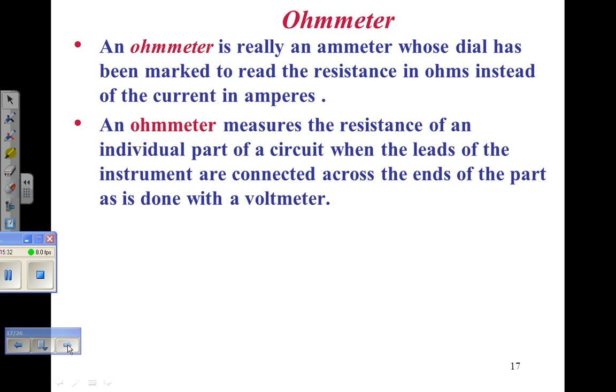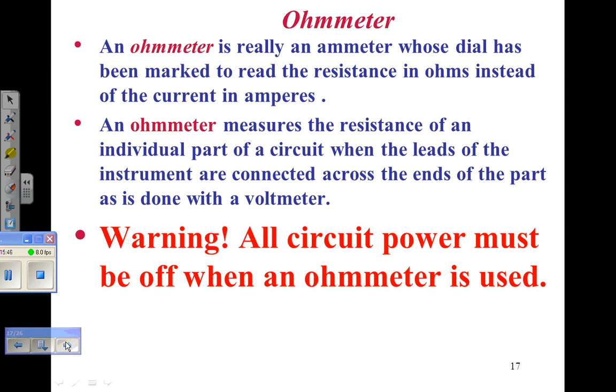Now, how do you have to hook up an ohmmeter? Break into the circuit? You would think, no, you break into the circuit, it's not parallel. But here's your big warning: make sure that all of the circuit power is turned off if you're going to use your ohmmeter, because your ohmmeter is creating a circuit of its own where you're sending out power and getting power back, and if it's getting 120 volts instead of 9 volts, you're going to burn up a fuse at best and maybe a meter.